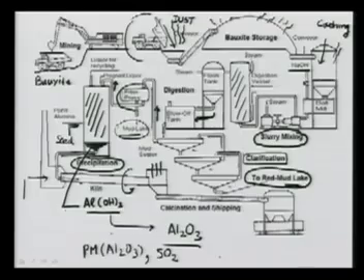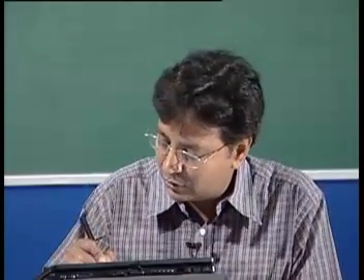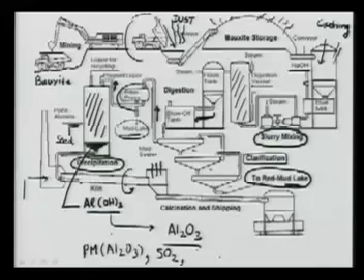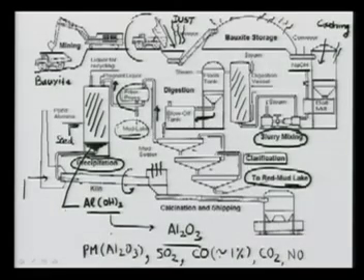It can also produce a significant amount of SO2. Why SO2? Because the furnace oil that we are firing will have sulfur, and that sulfur will be burnt out as sulfur dioxide. It has also been reported that a little carbon monoxide, of the order of about 1%, is also emitted, and of course the CO2 has to come out. And some very little amount of oxides of nitrogen are also expected.